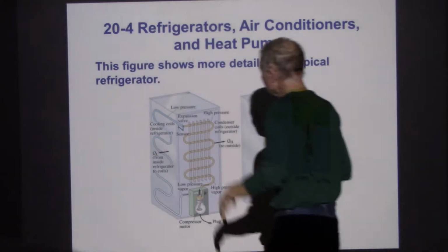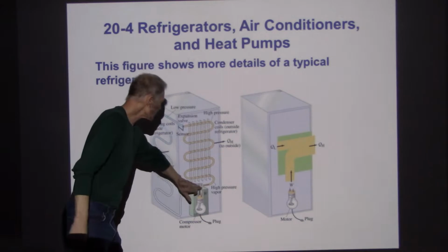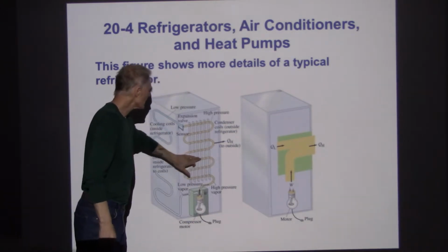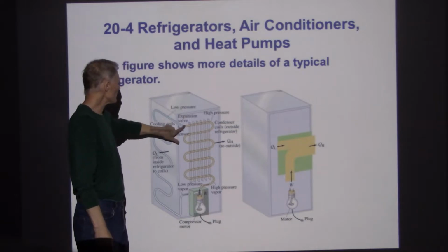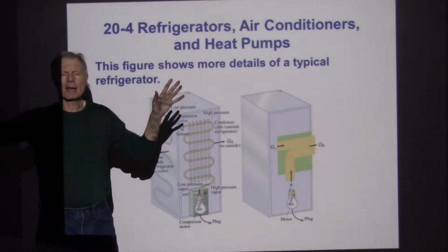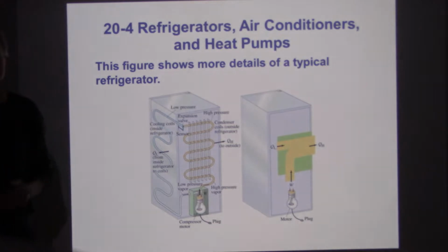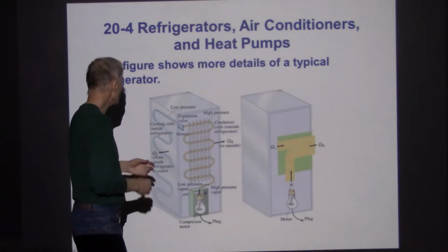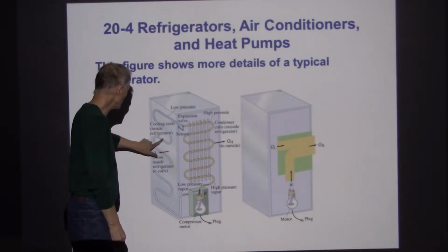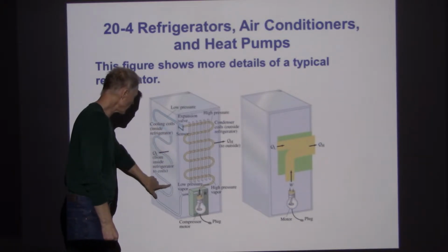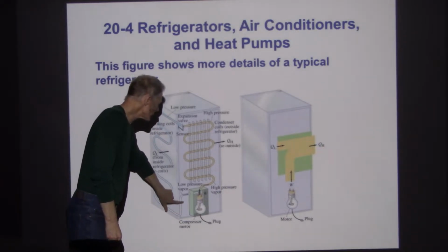So you can think of it this way: here's this region where it's being compressed, and the temperature is getting really, really high, and then as it passes through this valve, it expands a lot, and just drops in temperature. So all that energy is now gone from the coolant material. And so what we've got now is a coolant, a cold temperature region in the piping.